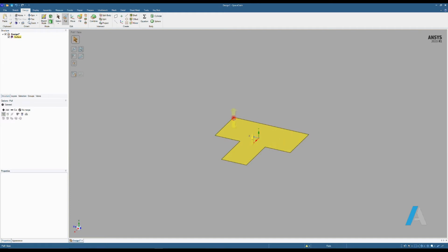This is a closed face. We only can pull closed faces, of course. So I'm going to, as you can see, pull it and in different dimensions. So if I want to add a dimension for my pull, I'm going to simply click on it and on your keyboard push the space bar. And it will let you input your dimension. I'm going to add 2.5 millimeter to my geometry or pulling.